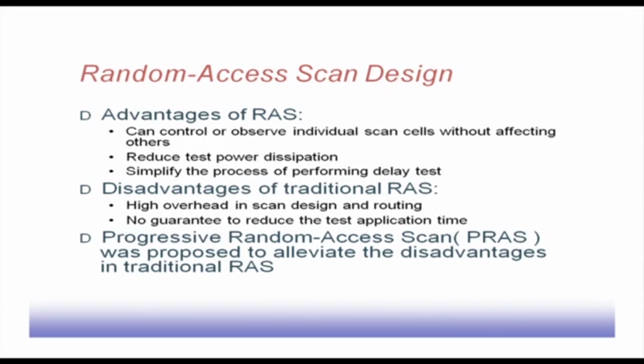Disadvantage: high overhead in scan design and routing. Now every scan cell has to be addressable. As a result I need to have a proper decoding of this scan address, so it becomes a bit cumbersome. And routing, because the scan cells are actually put onto the system by the designer. Test engineers cannot tell that they want the scan flip flop at this position or that position. That is done by the designer.